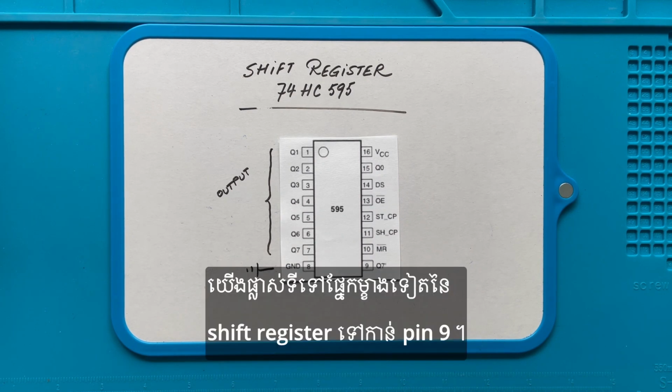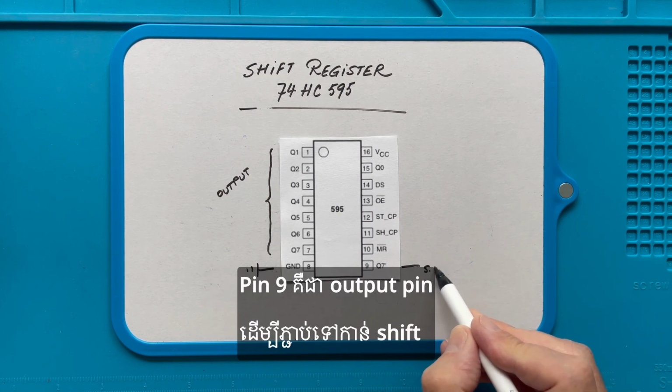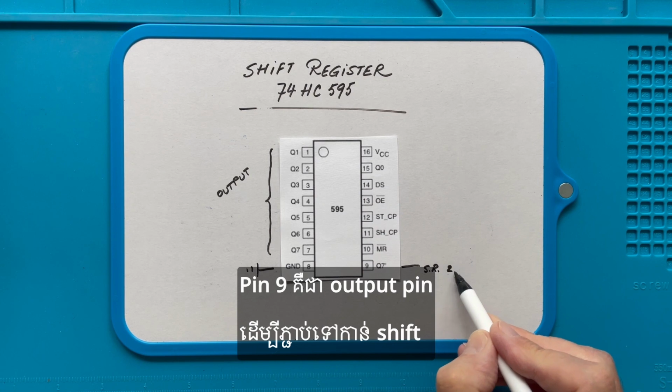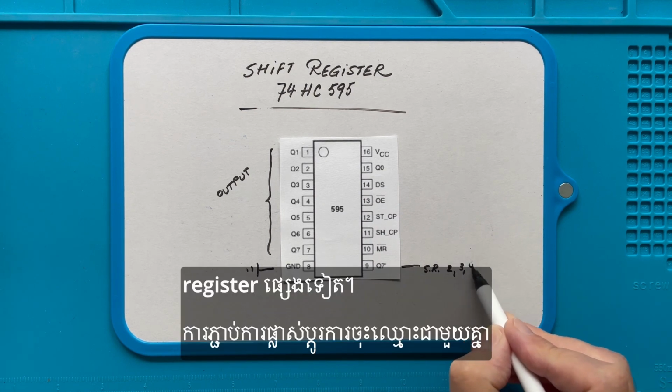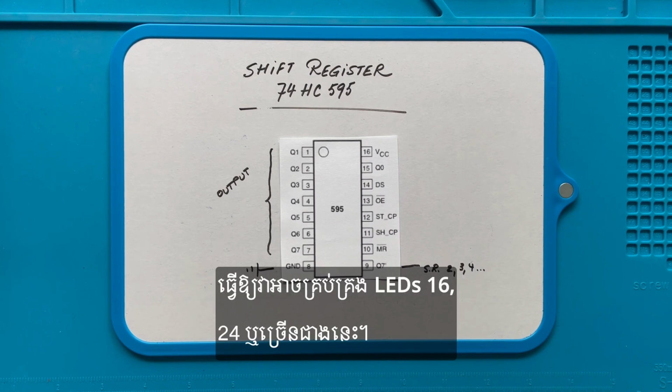We move to the other side of the shift register to pin 9. Pin 9 is an output pin to link to another shift register. Linking shift registers with each other makes it possible to control 16, 24 or more LEDs.